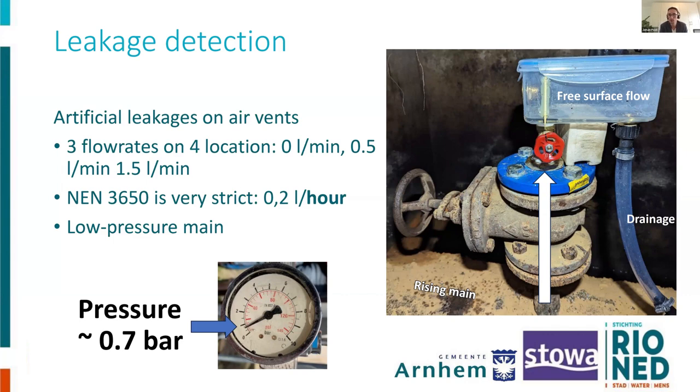But one of the problems for this pressure main is that the operating pressure is quite low. Increasing the pressure is not really an option, because then the flow velocity will be too high. That limits the application of the acoustic sensors which the inline tool uses to detect leakages, because that relies on hearing the outflow of water, which is governed by a pressure difference.